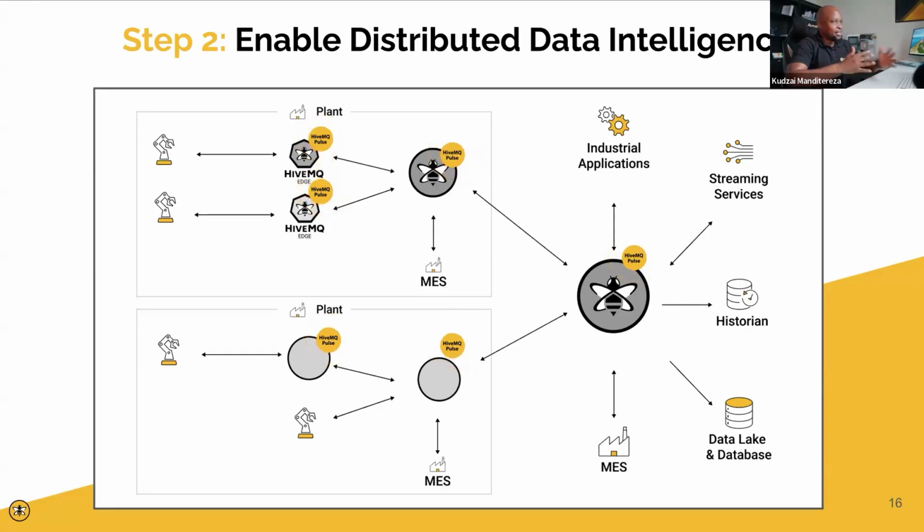That makes it easy for you to scale, because from one line it's a matter of just having that particular gateway that converts your legacy protocols into an MQTT protocol, effectively reducing it to plug and play. As soon as you commission a new line or add a new machine, it automatically gets published up into that central hub of information and becomes visible instantly. So it's easier to scale because you're plugging into infrastructure. You're not connecting application to devices or application to application. You're connecting devices and applications to an infrastructure.